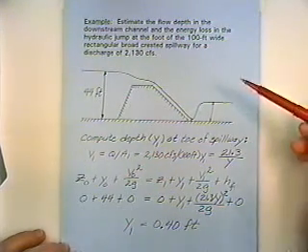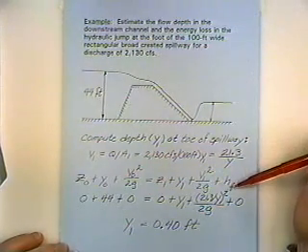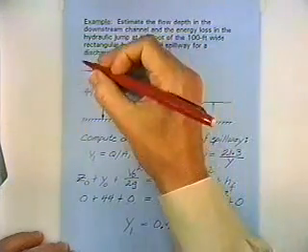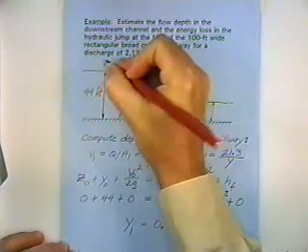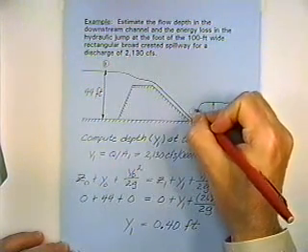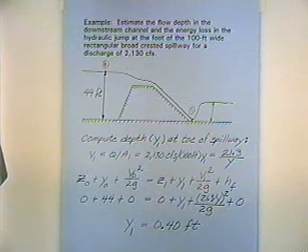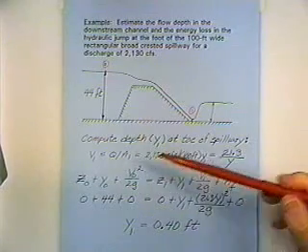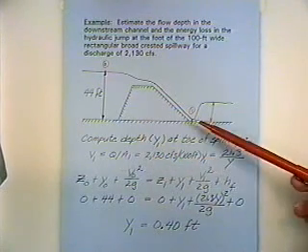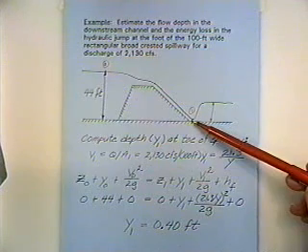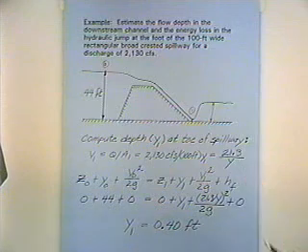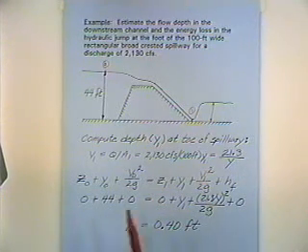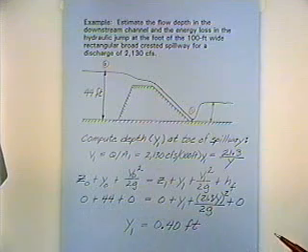We're plugging into the energy equation between two points. So pick a point there. I called it point 0, and picked a point here and called that point 1, and apply the energy equation between those two points. Velocity is discharge divided by the area. If we take the discharge there and divide it by the area there, we have the velocity. So I've got an expression for the velocity.